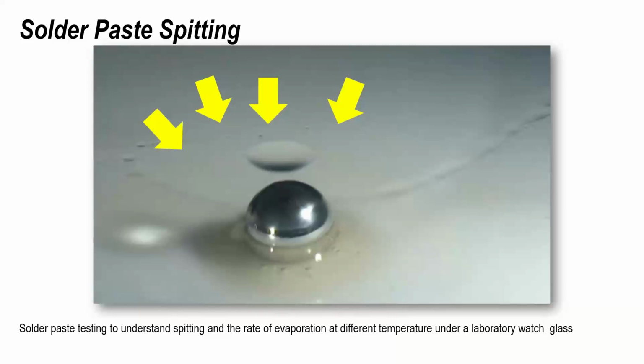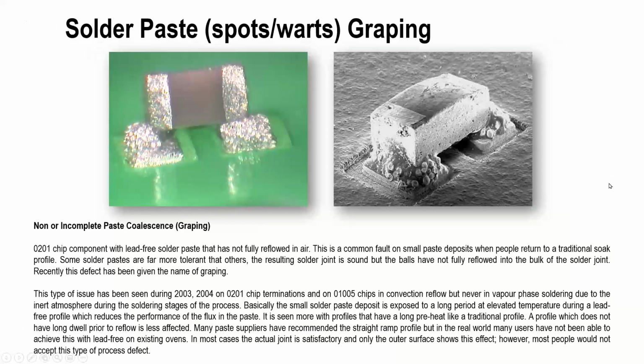The key thing here, obviously, is experimenting at the temperatures advised to us by the supplier. So getting the profile right to evaluate what's actually happening in the process. So very important. I included this as a defect with paste, and I know it's reflow and not printing, really. But it's something that I have seen on 2 or 3 occasions just recently on small chip processing.